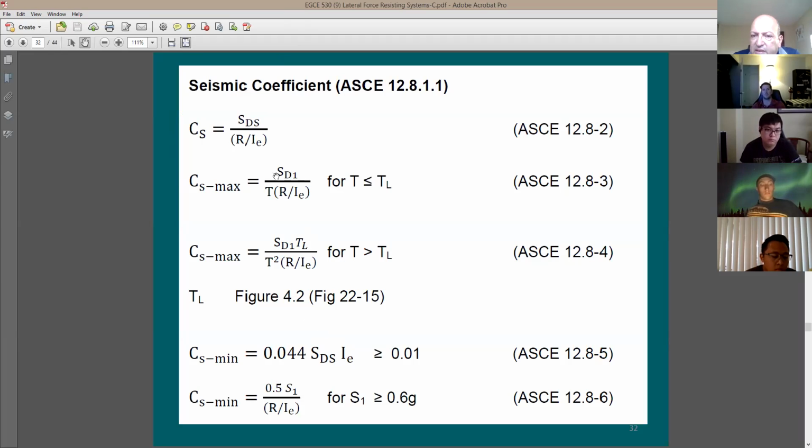The design equations, this is going to be like the famous static design or lateral force, equivalent lateral force procedure. And they're going to be all based on the code response spectrum. And as you see here, when the natural period of the structure is going up, we discussed this also last time, when this goes up, seismic design force is going to get reduced. This is the reason that the code, when it comes to natural period, gives you a limit, like a maximum value. Otherwise, you can't really use this natural period of the code.